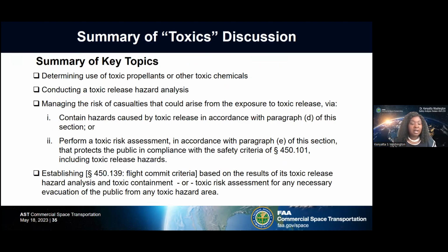In closing, as a summary of toxics key concepts, the FAA would like to just share some takeaways. The operators are primarily responsible for determining use and identifying toxic propellants, conducting a toxic release hazard analysis, managing the risk of casualties that could be a result of any toxic exposure by hazard containment, and performing a toxic risk assessment.